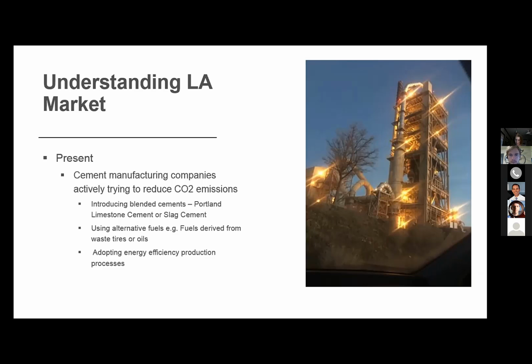So when you make these 1L13s with 13% less clinker in it, and then you're combining that with 50% of an SCM or a post-industrial product, you're really doing quite well and getting to some super low numbers in terms of the GWP or the embodied carbon of that mix.